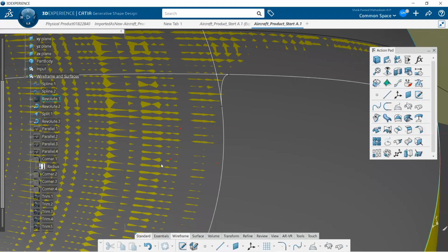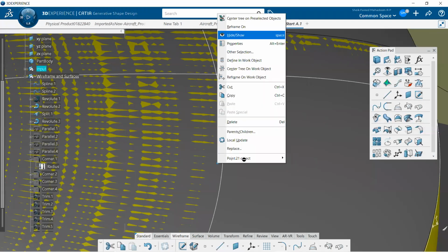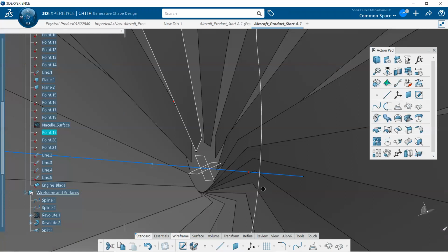Now I'm going to use the spline option. Before that, let's make this dot as the center key selected. Now just use the spline option. Select this side, and then select this spline. You can see an arc shaped profile is created. Then click preview and say okay.